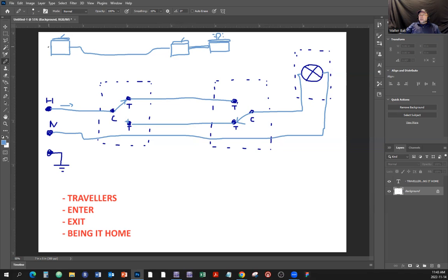And over here, we're just going to get the 2 screw connector that we mounted previously. And we're just going to get the NMD90 cable 14-2. And we're going to bring the supposedly power to it. So that's how this box is going to be powered. And over here we're going to have single conductors going there and single conductors going there. And we're going to connect things. Now, let's see, okay, so here is this conduit right here, and here is this conduit right here.